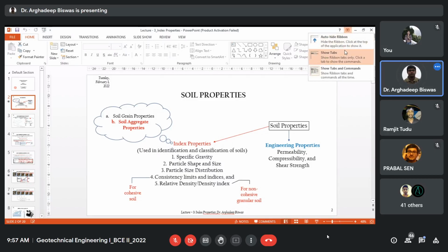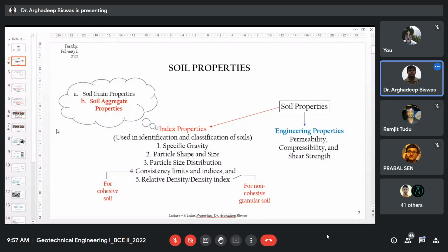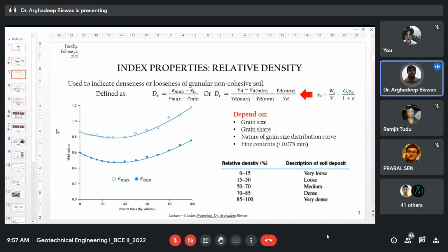Let's have a discussion on relative density first. It is represented by your natural state with respect to the maximum and minimum possible density that you can achieve. Here we mean the non-cohesive soil or sandy soil, because the presence of water does not have any influence in providing adhesiveness in a non-cohesive soil mass. Therefore, their properties are defined with respect to their density state, that is, where they are with respect to the maximum and minimum density that could be possible with your given soil.